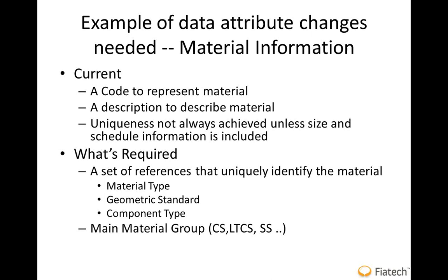However, if for any reason they change the order of the text in this description, let's say they want to say pipe, LTCS, and maybe B333, which is the material, and they put B333 before the LTCS, as a human I can still understand it, but a machine will find it difficult to decipher this kind of description.